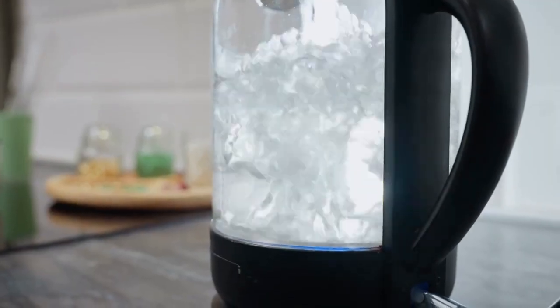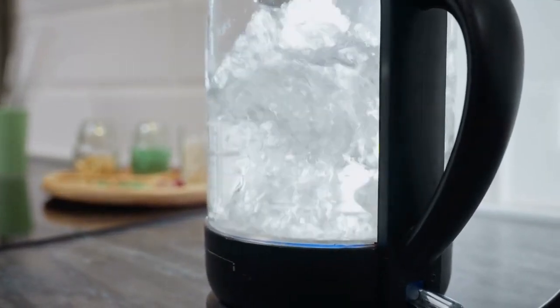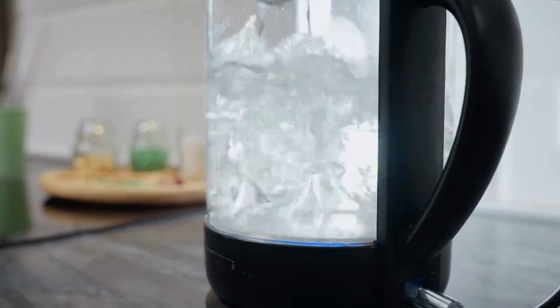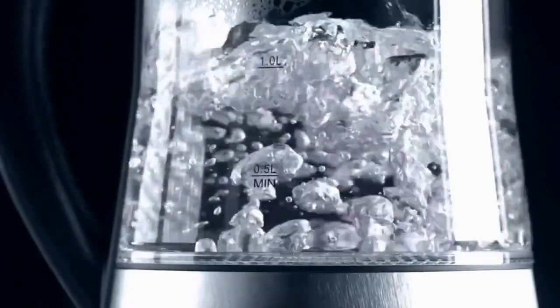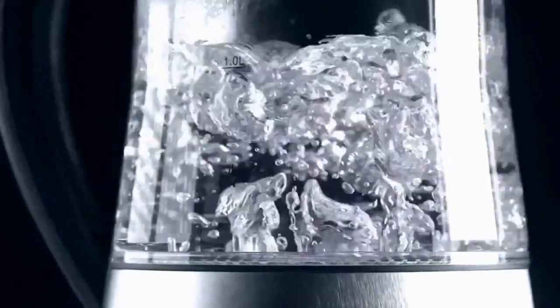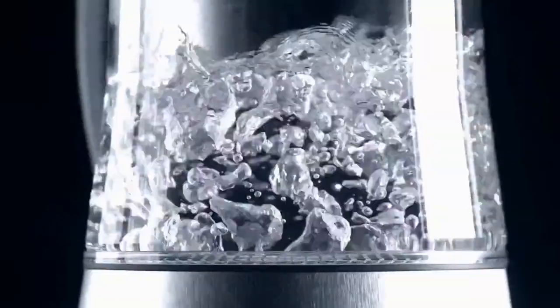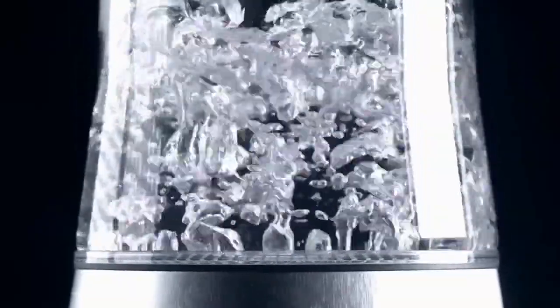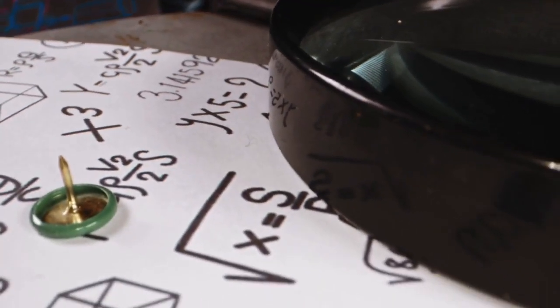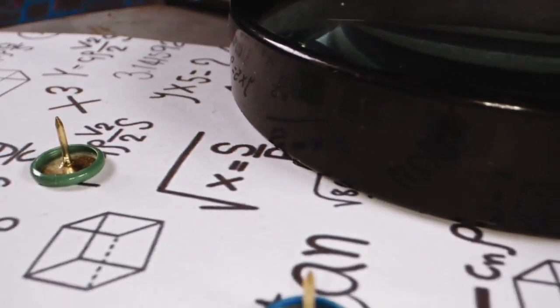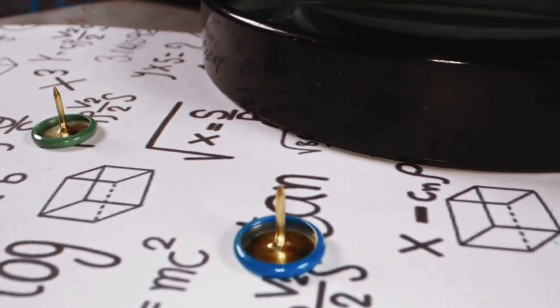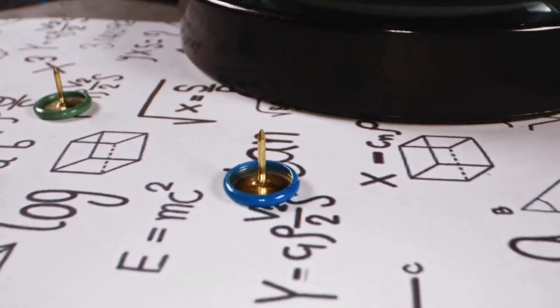This is the energy needed to break the bonds holding the water molecules together as a liquid and allow them to escape as a gas. Once every last drop of liquid has turned into steam, still at 100 degrees Celsius, you have what is called a saturated vapor, and its total energy content is now represented by its enthalpy, Hg. So, you can see that the final enthalpy, Hg, is just the initial enthalpy, Hf, plus the energy you added to make the phase change, Hfg.